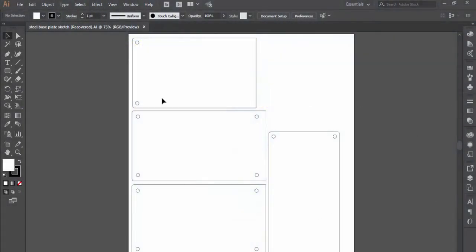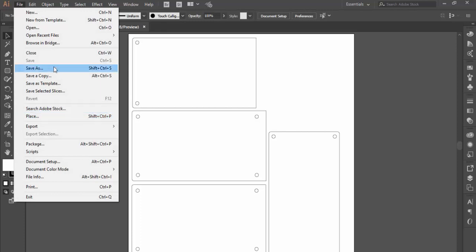After looking at this and considering the steel that I have on hand, one of my rules that I've always operated by is design to the materials and tooling that you have. The steel that I currently have right now is 2 feet by 4 feet. I had it sheared and cut to that size, 1/8 inch thick. So what I want to do now is to think a little more pragmatically,